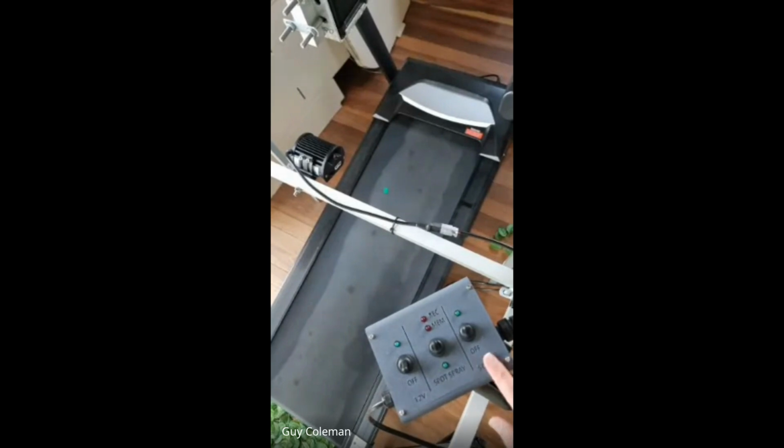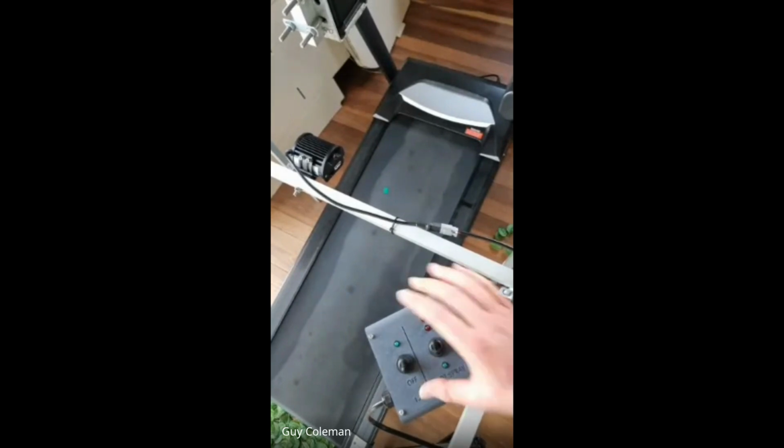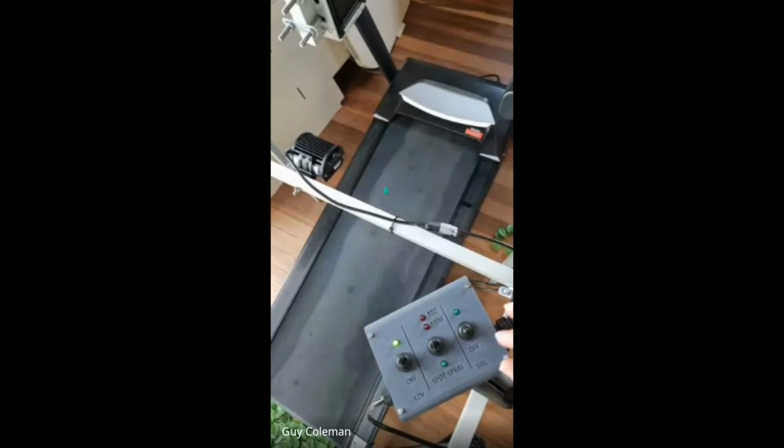So what we have is this controller, as I mentioned. We have to switch it on first. And we've got power coming from a power supply just over to the right, but you can provide any, as I said, 12 volts is ideal, probably what most of you have on farm equipment, but up to 27 volts is what's supported by that driver board. But of course, be careful of all your downstream. If that's not supporting 24 volts, then that will get burnt out. But right now, the OWL is booting up, and we'll also turn on the treadmill.